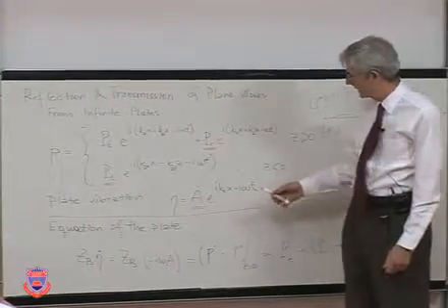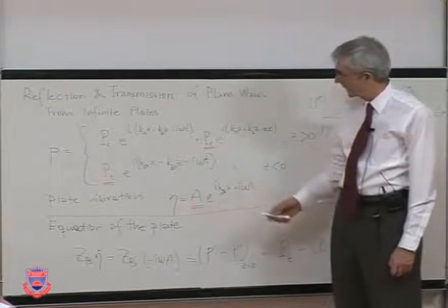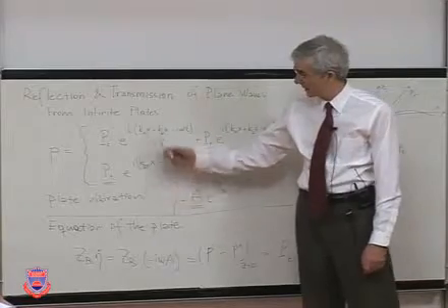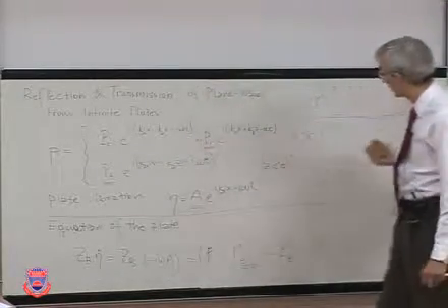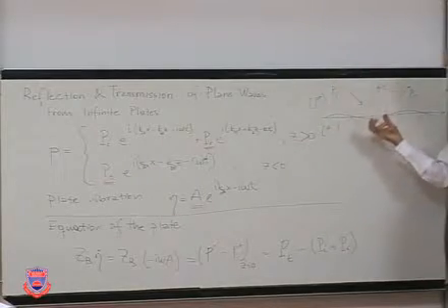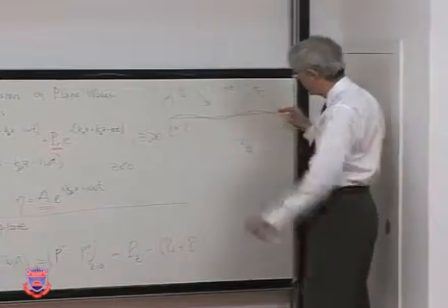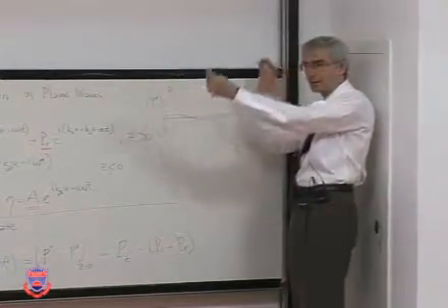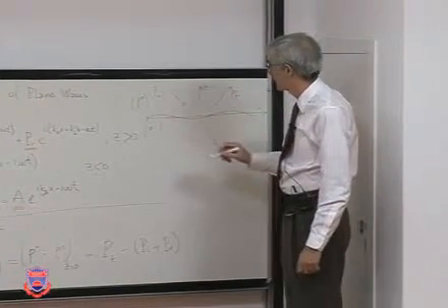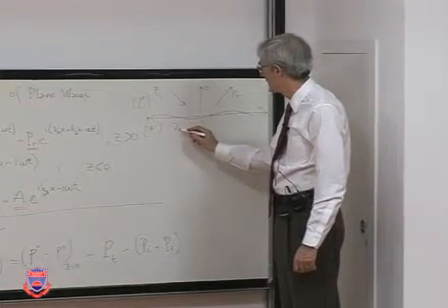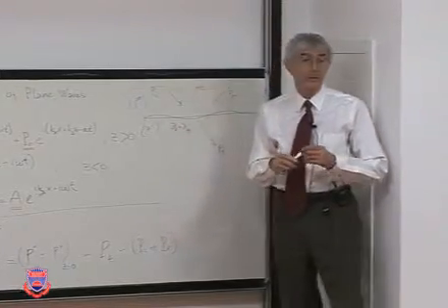Now, the important thing here is x. Kx must be the same in all of them. What is driving this? Energy is coming from the incident wave. That's the driver, that's the force. And what the plate sees when that pressure comes is its footprint in the x direction, meaning lambda x, which becomes the bending wavelength of the plate.